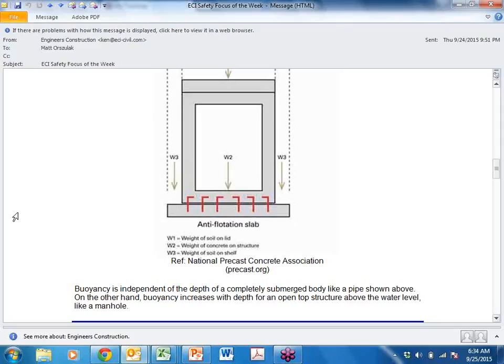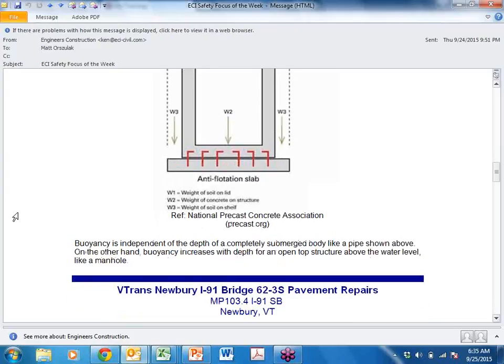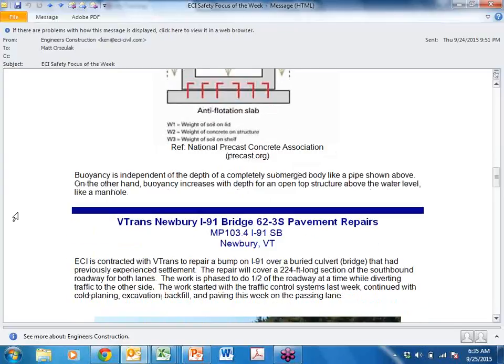That's right. And sometimes a job site might be partly complete, say putting in manholes, and then maybe you get a storm and maybe your excavation is not backfilled all the way. You could have a trench full of water, you could possibly get a manhole that pops right out. We've had it happen. I'm sure it's happened to just about everybody. If it hasn't happened to somebody, it will happen to somebody, right?